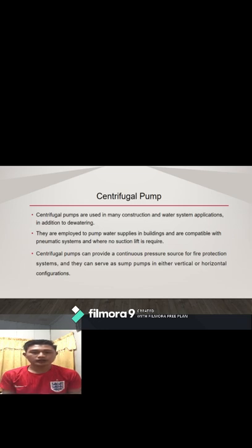Centrifugal pumps are used in many construction and water system applications. In addition to dewatering, they are employed to pump water supplies in buildings and are compatible with pneumatic systems where no suction lift is required.